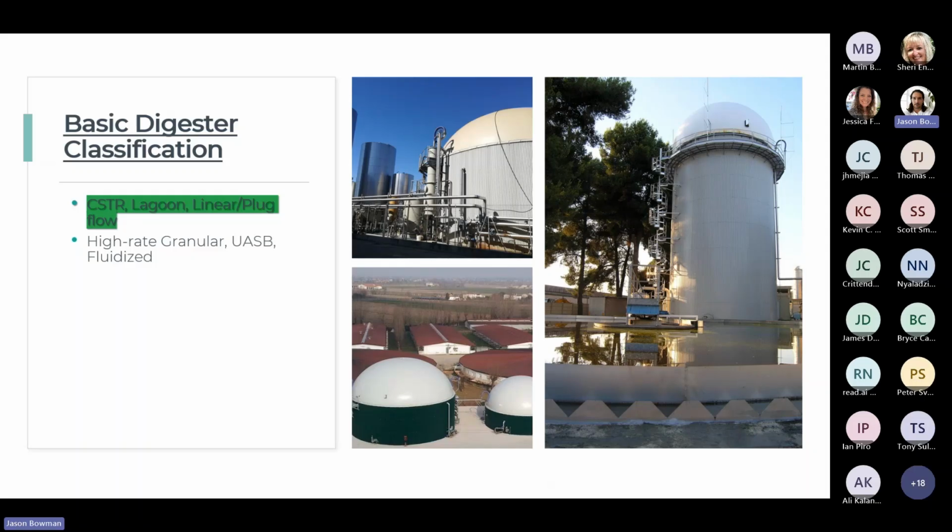So quickly going back to the various forms of digesters and how recuperative thickening can or cannot be applied, knowing where it cannot be applied is equally as important as knowing where it can be applied. Recuperative thickening, again, is applied anytime we have a suspended phase biota or suspended phase biomass, really like a normal bacterial flock from digester systems.